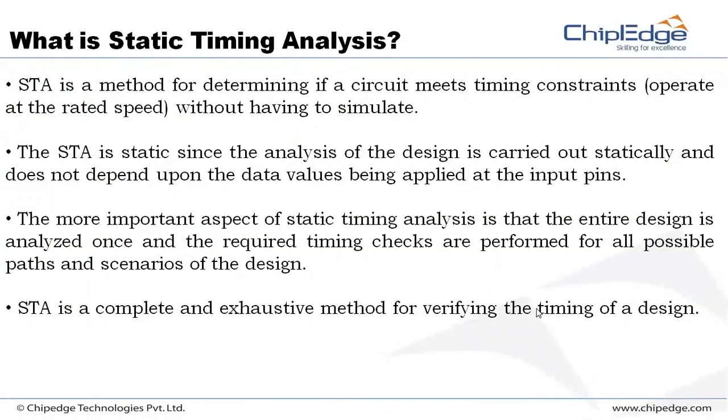With that, what is static timing analysis? Static timing analysis is a method for determining if a circuit meets the timing constraint. I told the timing constraint. Timing constraint means that frequency. Will it work at that frequency or not? The static analysis does not depend on the input values.